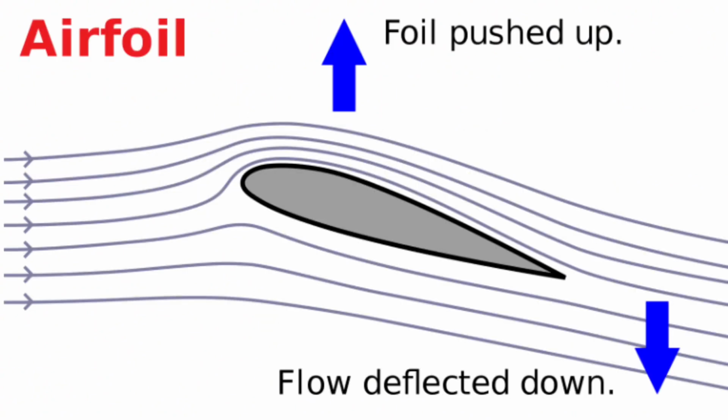Now let's talk about what is an airfoil and the terms associated with it. An airfoil is designed to obtain reaction from the air moving over the surface. The reason why we have airfoils on the airplane is in order to create lift. Camber is the curvature of the upper and lower surface of the airfoil. Some other important aspects to know about the airfoil are the leading edge, trailing edge, and mean camber line. The mean camber line is the average of the curvature between both the upper and lower surfaces.